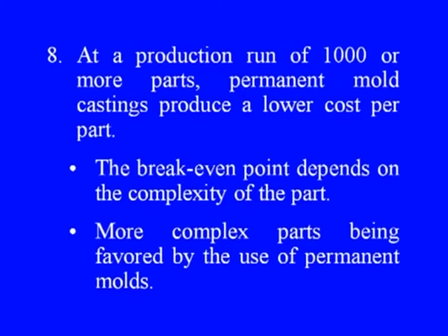At a production run of 1000 or more parts, permanent mold castings produce a lower cost per part. The break even point depends on the complexity of the part. The more complex parts being favored by the use of permanent molds.